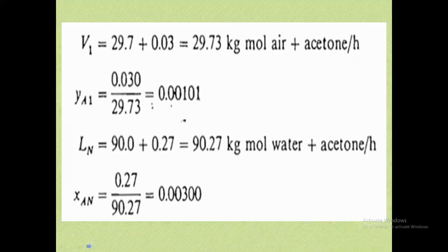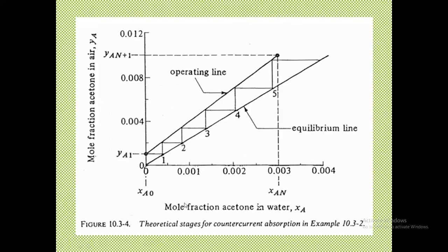So I had that part enlarged in here. What you're going to do is plot the X and Y pairs, in terms of the 1 and 2 representation. So this is for the 2, meaning this is y2, x2, and this is for the 1. You have here xa1 and ya1. So these are the pairs xa1, ya1, and ya2, xa2. Now, this one starts at the bottom of the operating line. This is the equilibrium line.